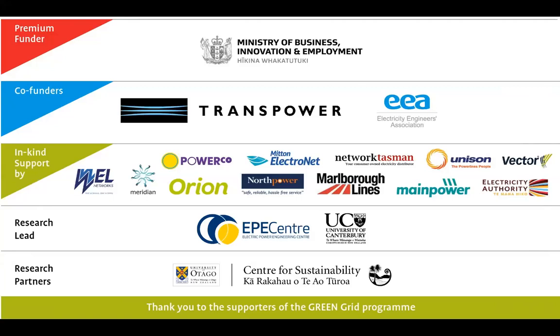Yeah, so if you want a little bit more detail on that, what I've looked at is a day-ahead optimization routine, which manages EV loads in LV networks in order to try and smooth out the aggregated load on the transformer, and that's the load due to EVs and non-EV load. So initial results and findings from that are that having as your optimization objective function trying to smooth out the transformer load, without consideration of how you do that downstream of the transformer, can actually have counterproductive results.